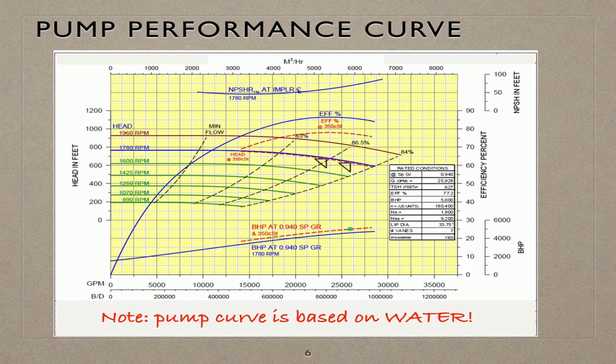As we can see from the pump performance curve, the shape of the head versus flow diagram should be something like this, depending on the pump parameters. Such curves are known as pump performance curves, which can be determined experimentally by manufacturers by using a flow meter and pressure gauges. As we can see from the curve, NPSHR increases with flow.